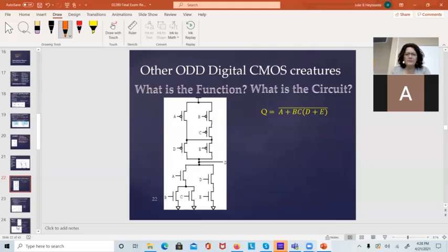This is something fundamental. This is something I really care about, is being able to draw these CMOS circuits. Now, if I look at this, remember our parallel, our NMOS. I always do the NMOS first. Parallel is ORs. Series is AND, and then I put a bar over the whole thing because when that function's true, it's going to pull the output low. Invert the result.